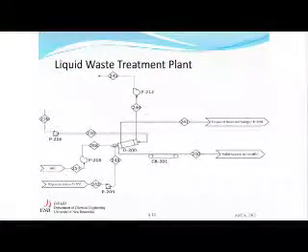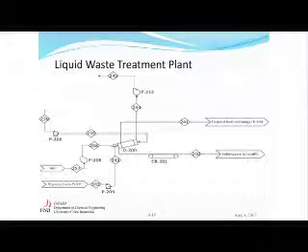The liquid waste stream from the wet flue gas desulfurization unit will flow to the indirect fire rotary dryer, which evaporates the water content of the liquid waste, and it will be sent to the pond heat exchanger to heat up the water in the algae process, which George is going to explain in a minute. And the solid waste can be safely landfilled.